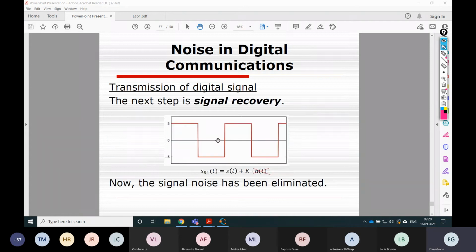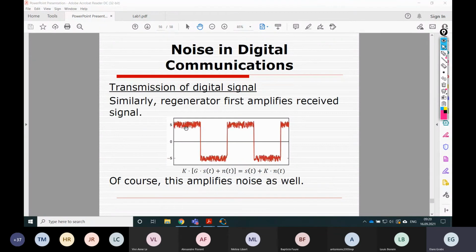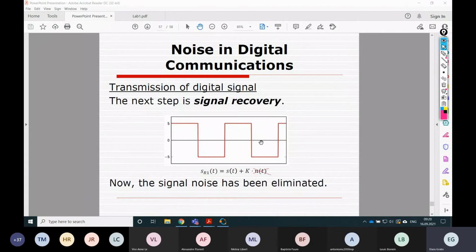This clears all this noise. We remove the noise by making a decision. So this is 1, this is 0, this is 1, this is 0, and we send this clean version further. Now it's understandable that we can repeat this process as many times as we'd like, and in the end we'll still get this clear signal.